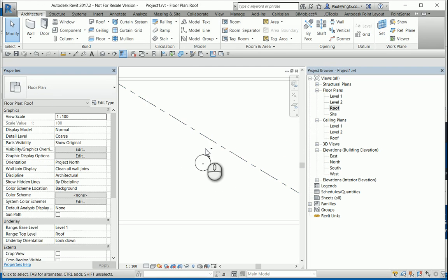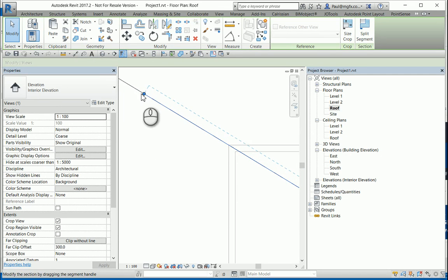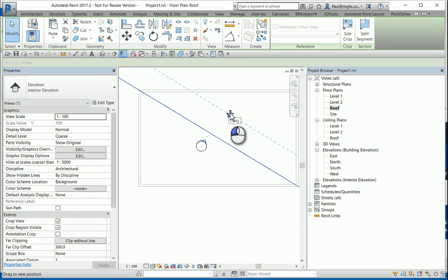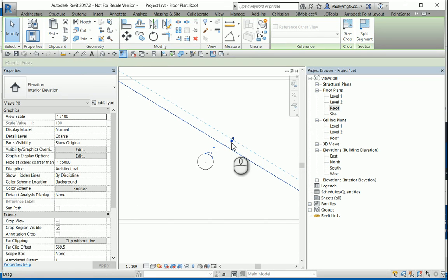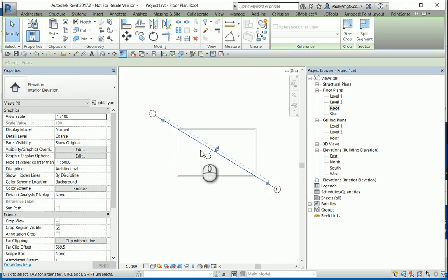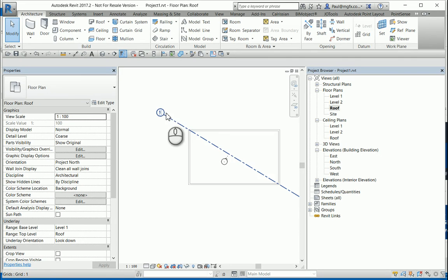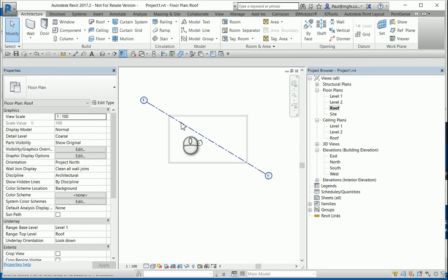What to watch out for though is notice how small the section box is. It's sectioning straight directly from that grid line, and then it is carrying onwards from there. So you're only going to see half of what you're sectioning through, and then only a very short distance. But it will allow you to create that extrusion very easily. In addition to that, I'm going to need 2 more grid lines just to give me guidance as to where I'm going to create my trusses. I could create the trusses just fitting into the walls over here, so I could use the walls.